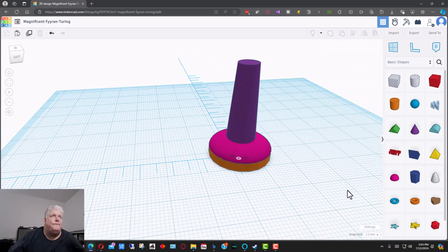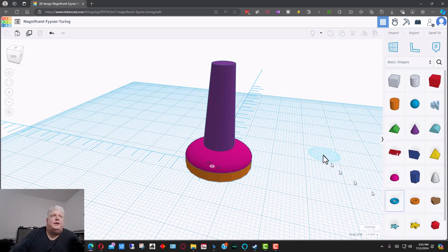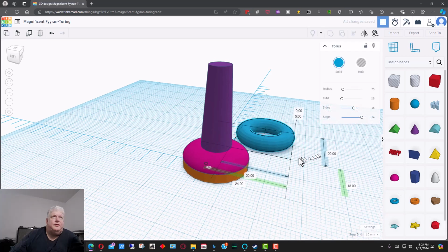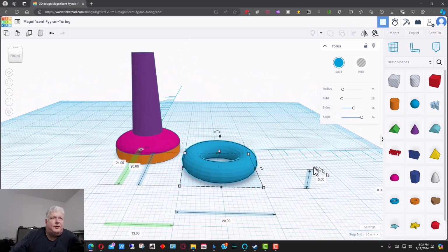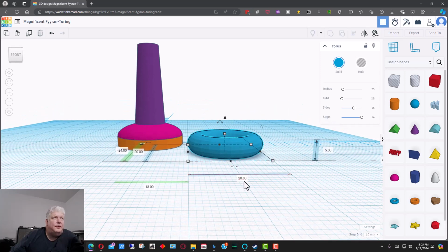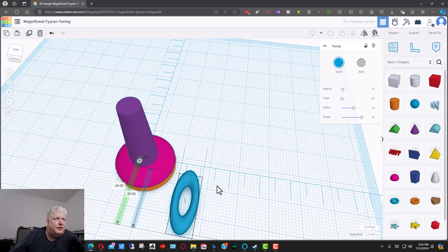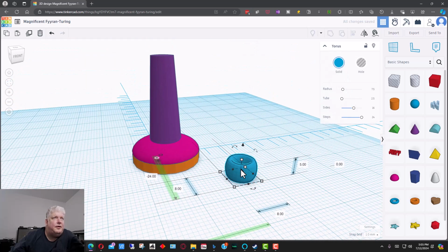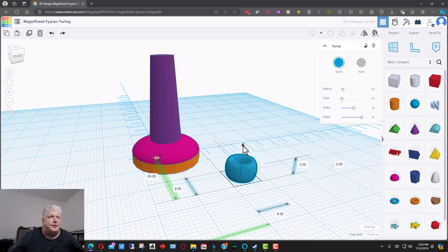All right. So now the next thing that we can do is we can take this shape right here, and we're gonna go on this side, and we're gonna make this let's say 7. This one's a little, let's make it 8 here. And this is still 20. Let's make this 8 to round it back out again. Oops. If you hit Control Z, it will undo something in case you kind of stretch something out by mistake.